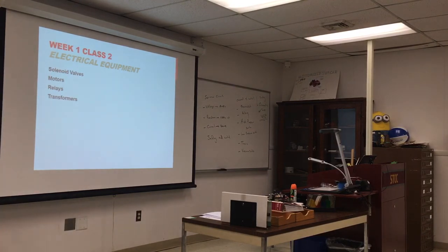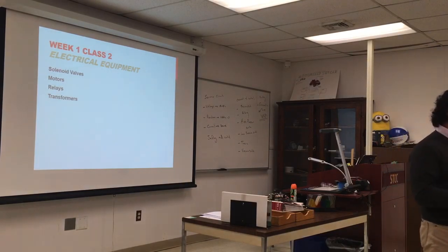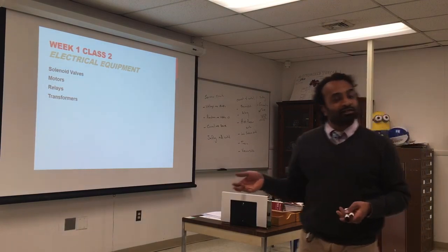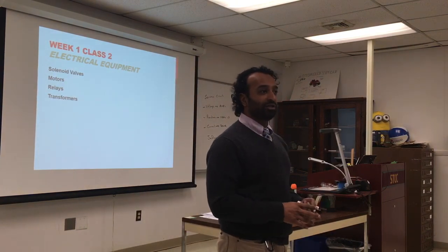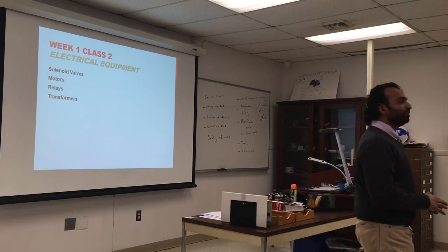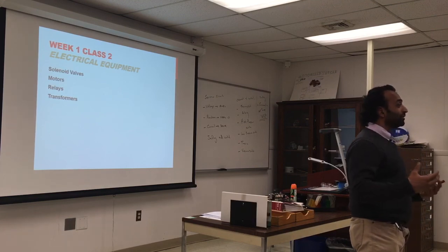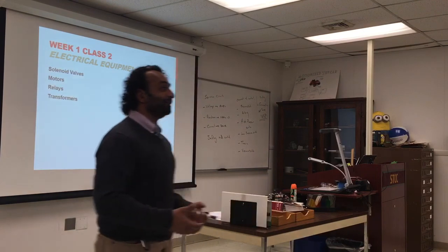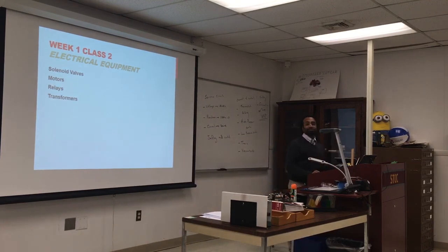So mostly nitrogen, and oxygen is 20%. Remember that, because when you do combustion testing, you have to measure the oxygen. If you have less oxygen, it means you are burning the oxygen, which is your goal. It's very difficult to burn all of it. You're going to burn most of it, so 14 or 15% is pretty good. How much oxygen do you think you take with each breath? Out of the 20%, maybe 2 to 3% if your lungs are really good. If you're an athlete, you'll absorb more. If you're a smoker, probably 1%. That's why you are short of breath, because your body cannot oxygenate quickly. So you want to have really good lung function.